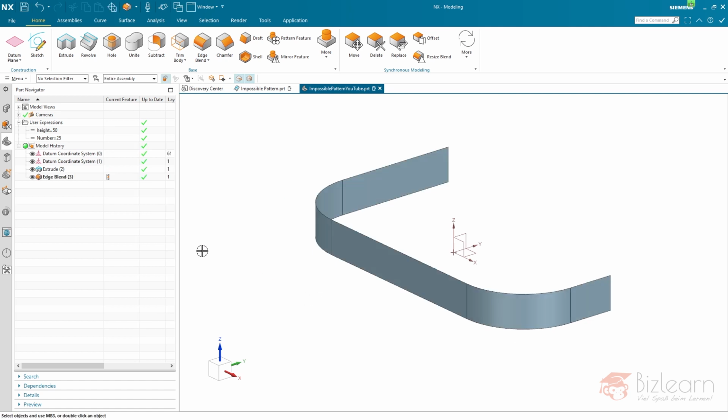And the next step is the creation of our intersection curve, and that's important because right now we've got two planes we can use, two top planes we can use, and I want to create references to my second coordinate system only, not this one. Because if I'm moving this one afterwards, of course, every relation shall be moved parallelly. And that's why we shall avoid right now at this point to create relations to this coordinate system. But as you can see, that's what I did with the extrude. That was a mistake you should avoid.